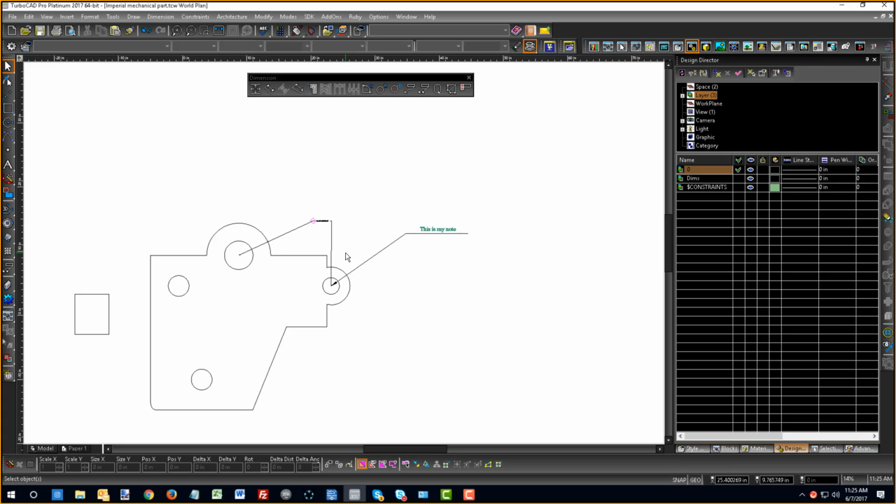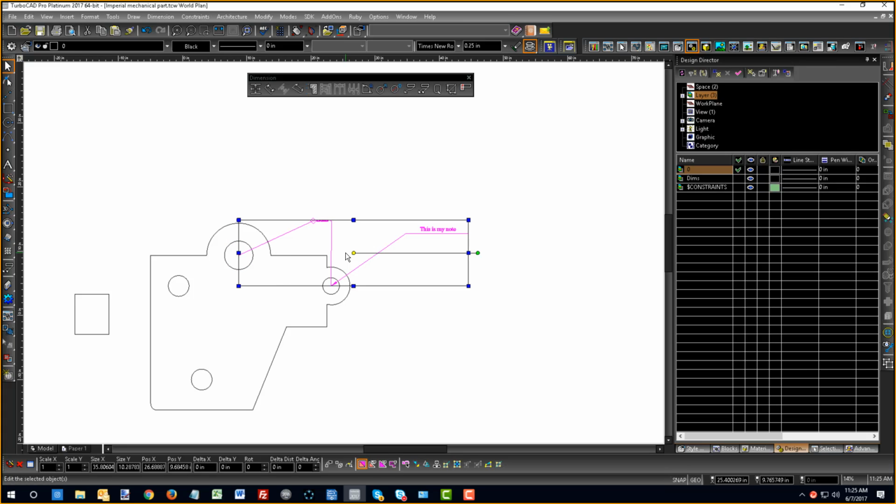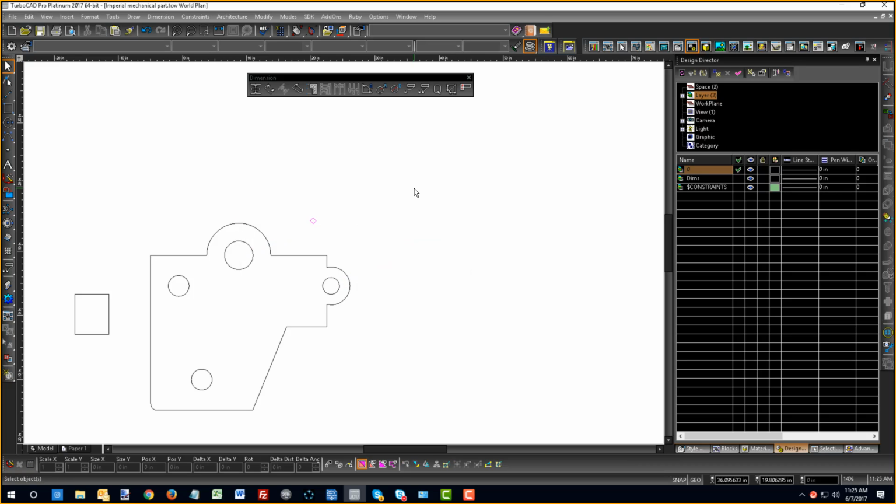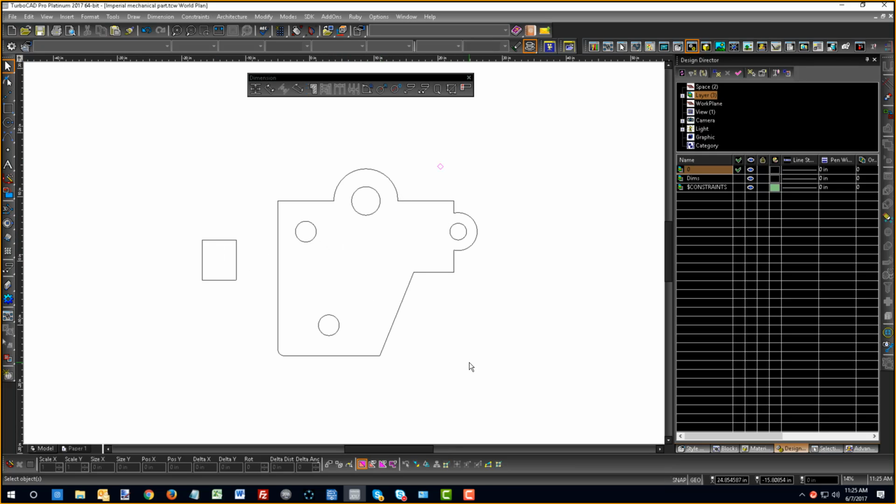So F6 and F7 can be used in this case. This is F7. I hold the shift key down, hit F7 twice, and now those last two objects that I drew, which were those leader lines, I can highlight, and I'll just hit delete to get rid of them. So I'd get used to using the F6 and F7 keys, practicing those, because they come in very, very handy for a quick way to select objects, especially if you've just drawn them.